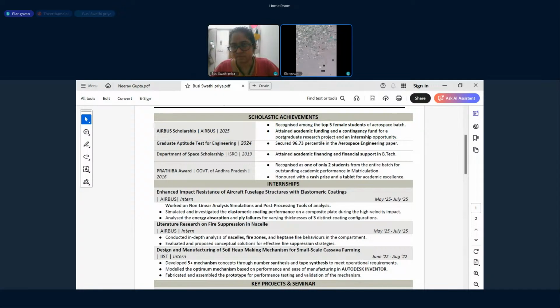M x double dot plus C x dot plus K x is equal to F. If the external force depends on x, x dot, or x double dot, that means displacement, velocity, or acceleration, then remember: inertial force is M x double dot, damping force is C into velocity x dot, and displacement force is K into x.